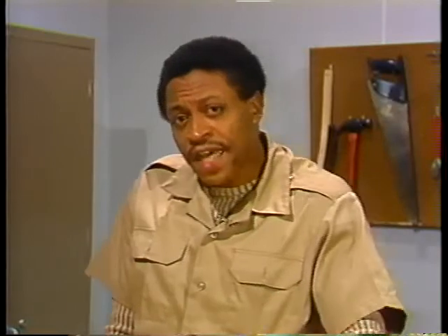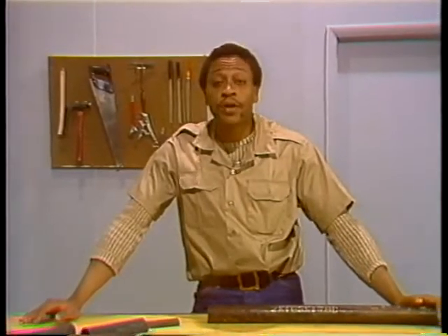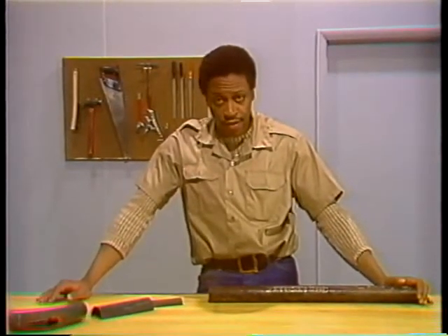Our purpose here is to cover tube repair techniques. Generally, we will cover how these repairs are made so that you'll understand what has to be done to repair a boiler tube. But first, let's discuss why tubes fail. There are 5 basic causes of boiler tube failure: overheating, corrosion, erosion, mechanical stress, and material defects. Each of these weaken the tubes and reduce their ability to contain pressure.